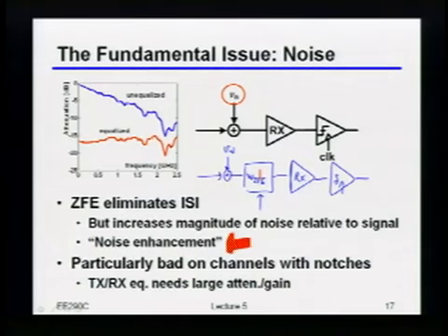When you talk to the comm guys, they're really focusing on that KT noise floor. That's really what they're mostly focusing on. But this same idea also applies even if you build it with a real circuit. And by the way, even if you're not talking about real fundamental noise, sometimes people will tell you that something like this looks bad simply because you'd be amplifying things like crosstalk more, right? Because you're doing a high-pass filter, and the crosstalk might be high frequency, so you might be amplifying that. Other questions?